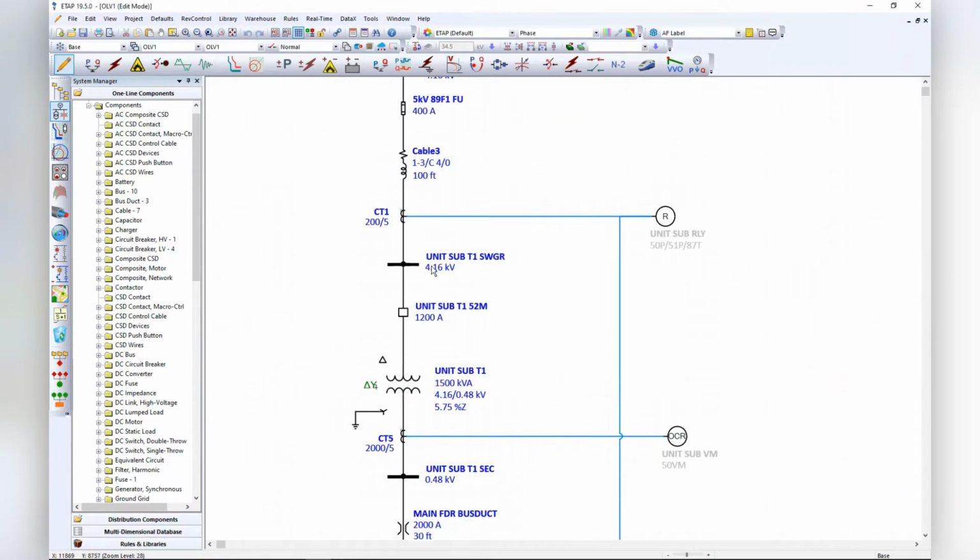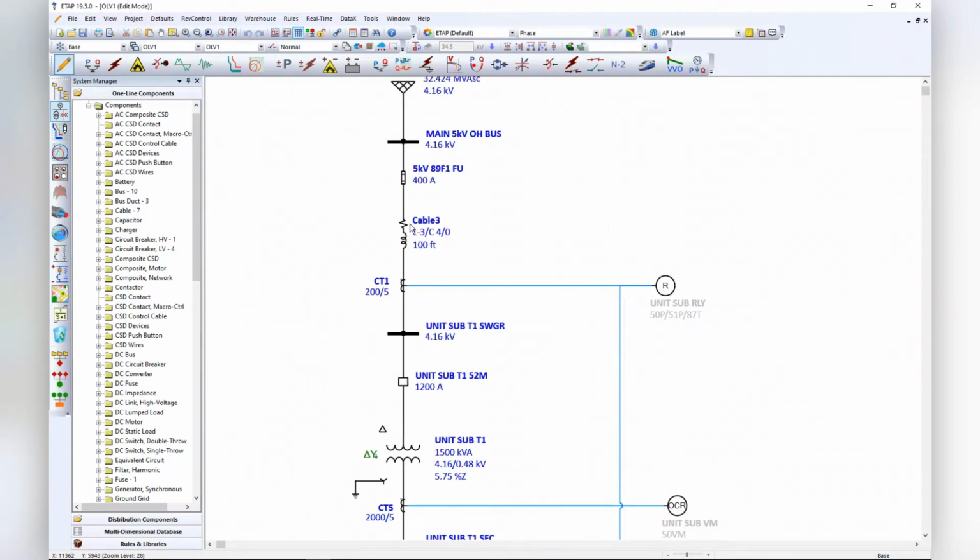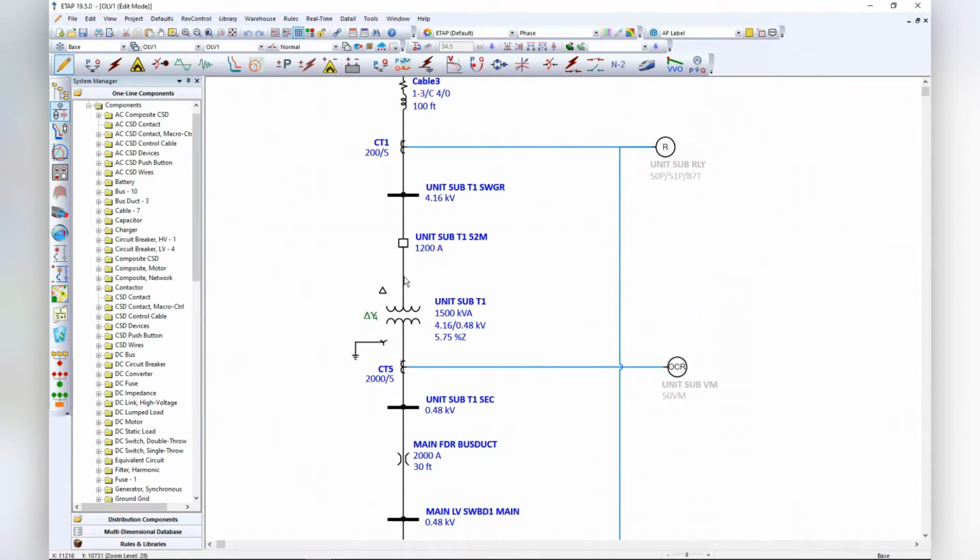And then I'm going to come on the primary side. And for now, the breaker doesn't exist. It's just a dummy breaker, because what I'm assuming is all the protection is done by this feeder fuse up here. I just have to have the breaker in there because I'm going to use it later on in the other scenarios.